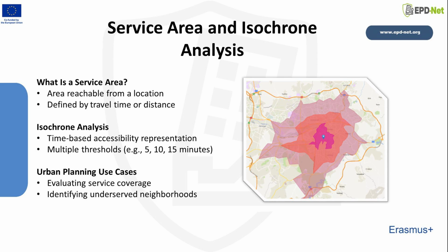Isochrone analysis is a time-based form of service area analysis. Isochrones represent areas that can be reached within specific time thresholds, such as 5, 10, or 15 minutes. These thresholds are particularly useful for evaluating access to essential urban services.